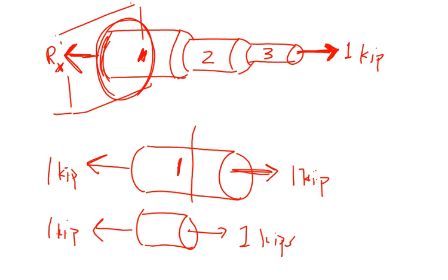Okay? And that's important. This is how you're going to determine internal forces in different segments. So what I refer to this as is you make a cut. Okay? You make a cut in the middle of your segment. Just make a cut somewhere. Right? And it doesn't matter where you make the cut. If you determine correctly where your segment is or what constitutes your segment, then it doesn't matter where you make that cut. The force at that cut will always be this one kip. Okay? And then that's the internal force.